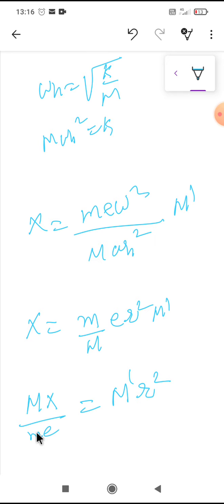As you can see, this is the total mass, this is the rotating unbalanced mass, this is the eccentricity, or the radius distance of the rotating unbalance, and this is also the amplitude. So this is a dimensionless quantity, and it gives us a dimensionless steady state amplitude as a function of the frequency ratio r and the magnification factor m dash.